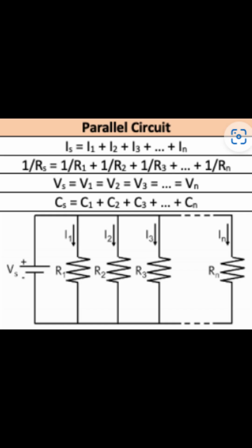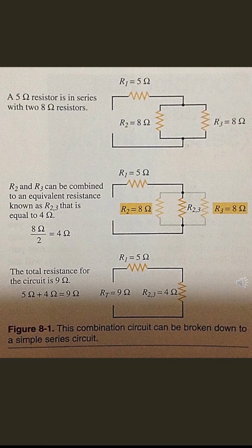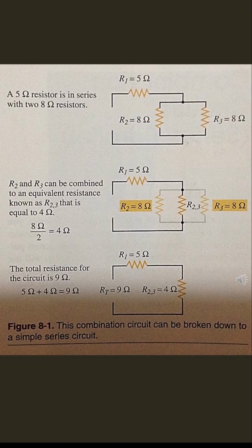When you come across parallel branches in series with other resistors, you will use your parallel circuit formulas to turn those resistors into an equivalent series resistor. The simplest way to understand this process is to work through some examples. 2 examples follow. Be sure to work through all of these steps. Reducing to a simple series circuit.